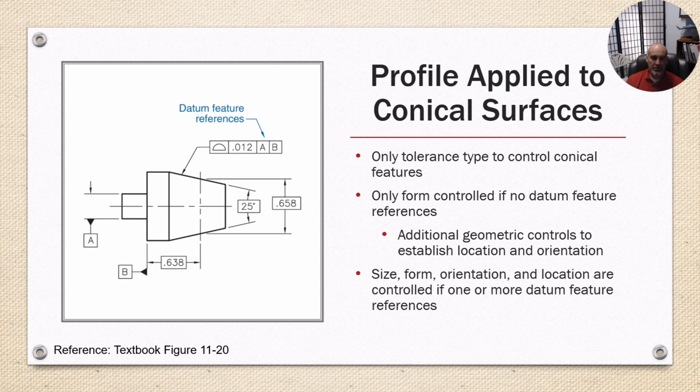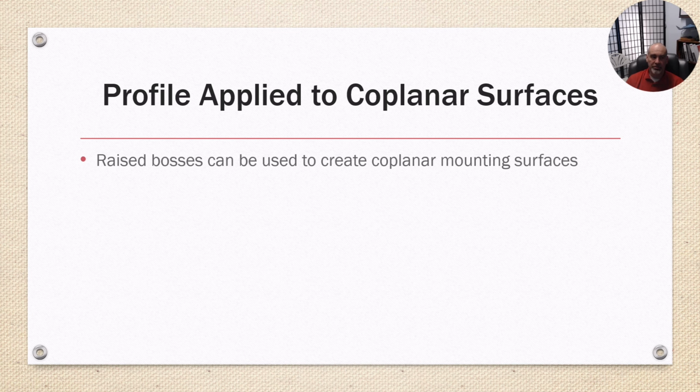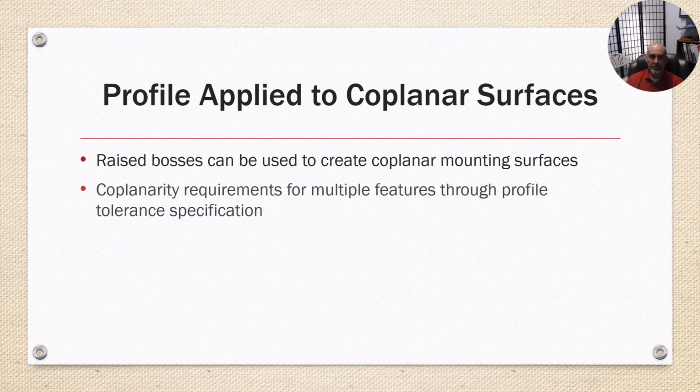Okay, profile applied to coplanar surfaces. Raised bosses can be used to create coplanar mounting surfaces. Coplanarity requirements for multiple features can be met through profile tolerance specification, with a well-defined meaning regarding form, coplanarity, and constraints of translation and rotation where applicable.